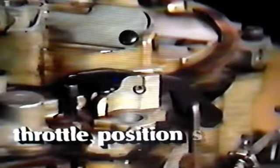The next important area of discussion is the throttle position sensor. In order to get to the TPS adjusting screws, you'll have to remove still another plug. To work on this plug, you'll need to get the accelerator pump arm out of the way. This is done by taking the punch and knocking out the roll pin that holds it in place.